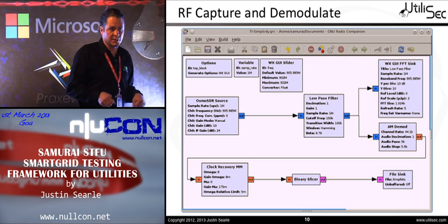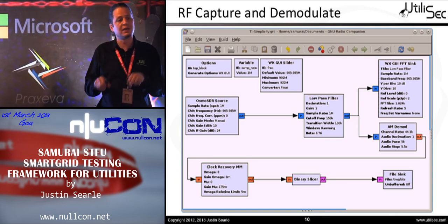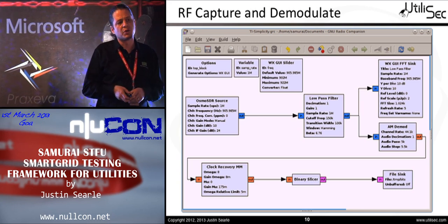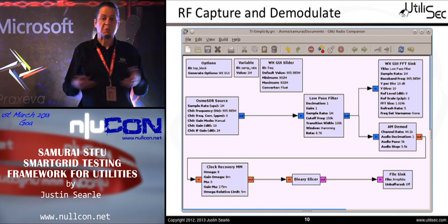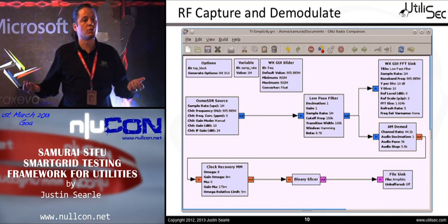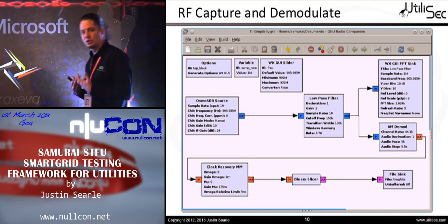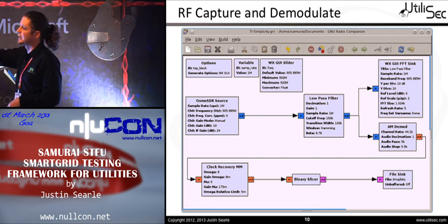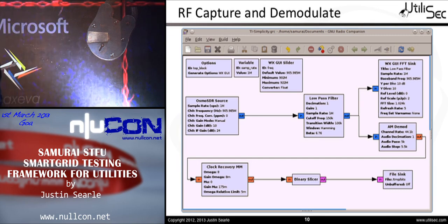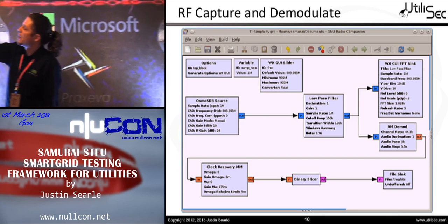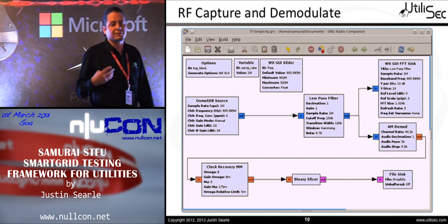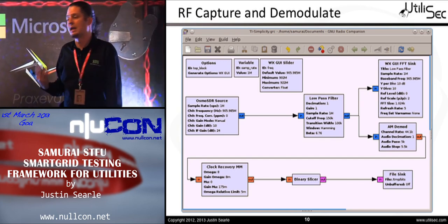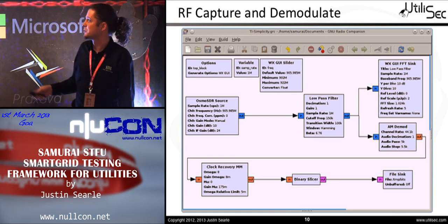However, inside of control systems and control networks, especially inside of the electric utilities, we have a lot of wireless protocols that are custom. A lot of wireless protocols that might be standards-based, but they're standards that security professionals haven't created any security tools for. So needing to have some good tools to be able to work with these custom protocols like GNU Radio and GNU Radio Companion, okay? And be able to try to provide some different types of block diagrams trying to work with some of these different protocols that you might come across and find inside of these systems.